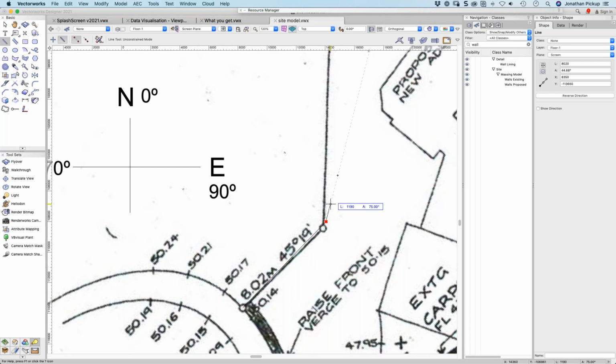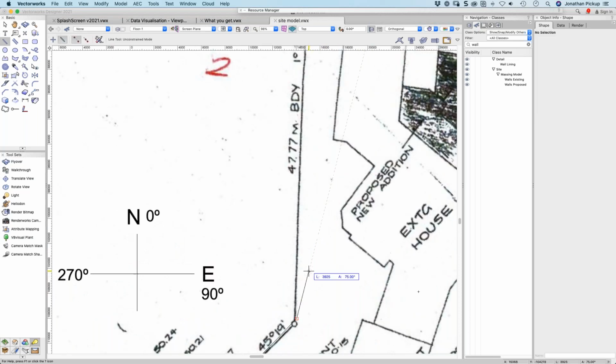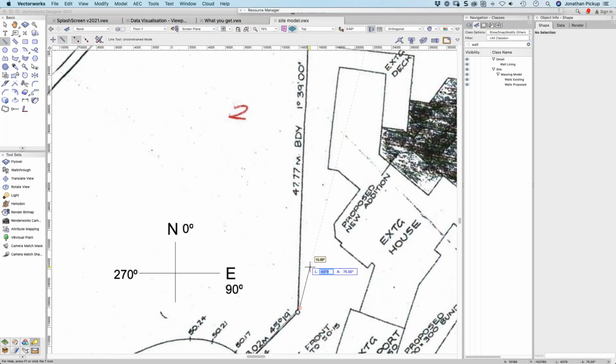The next line, Jane. I'll start from there. The length should be 47.77 m. And the angle should be northing and easting. And I'll go back 1 degree, 1D, 39 minutes, M for minutes. Do you put a dot between them?